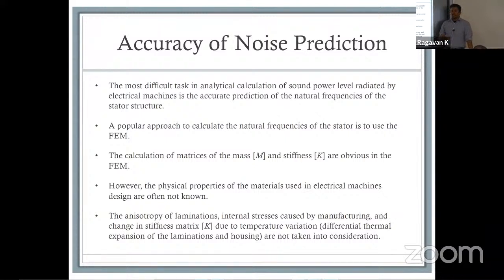Now the challenge here is if you set the wrong boundary conditions, right? If you tether the wrong point, because when you look at the motor, it makes a certain noise. If it is able to move about its source, the foot, and you make it a face mount while you're simulating, when you have actually put together a foot mount, your acoustic signatures are going to be off, because your housing relies on your ability to tell the simulation what parts of the motor are actually connected. So this can be a little challenging, and the most practical approach is to use FEM, so finite element methods.